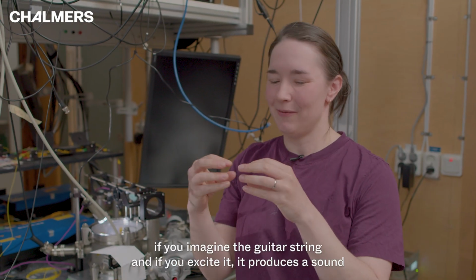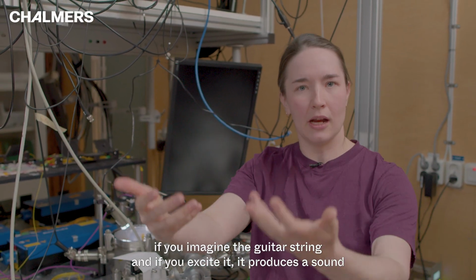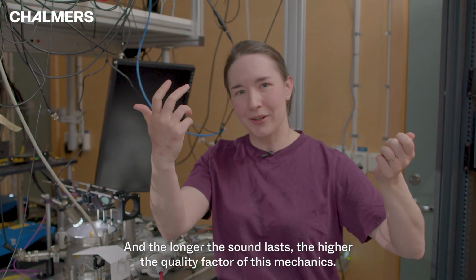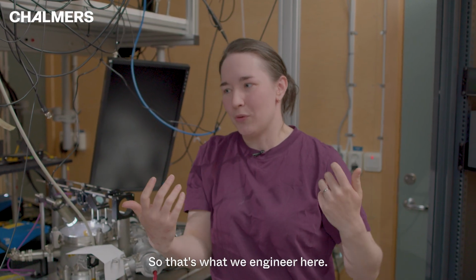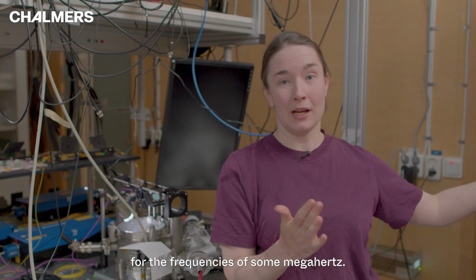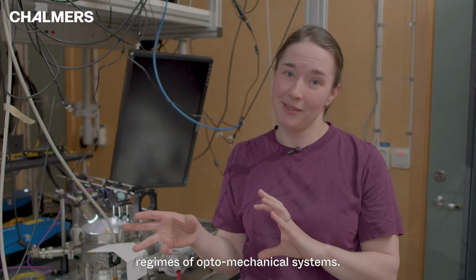So we already saw the oscillating frequency, that's just defined by the design, but the mechanical quality factor, easy to understand it if you imagine the guitar string, and if you excite it, it produces a sound, and you want the sound to propagate and last for a long time, so you apply more and more stress to the string. And the longer the sound lasts, the higher the quality factor of this mechanics. So that's what we engineer here. We engineer mechanical quality factors above 10 to the 8th for the frequencies of some megahertz. And these requirements are for certain regimes of optomechanical systems.